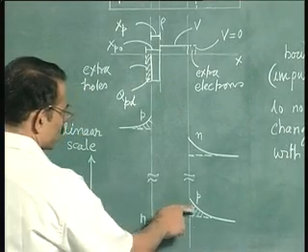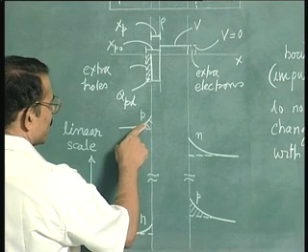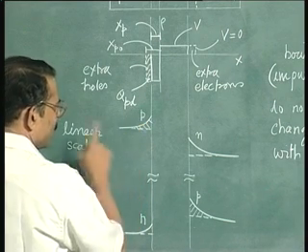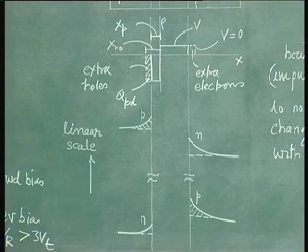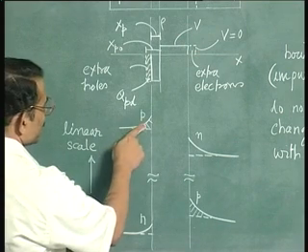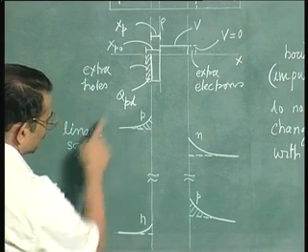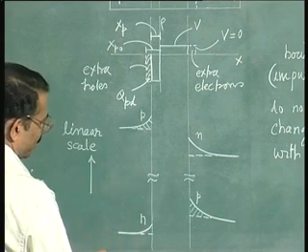Now you might have a doubt, how does this charge contribute to diffusion current? Okay, this is the majority carrier charge. Well, this is an important point. You must note that this charge is equal to this charge, because this region should be quasi-neutral.